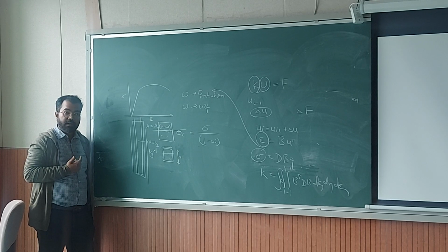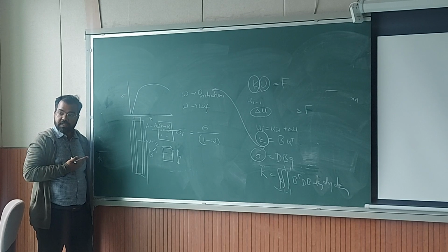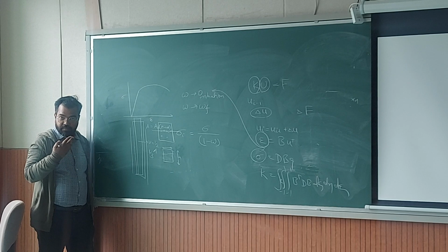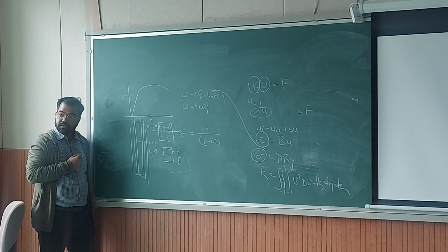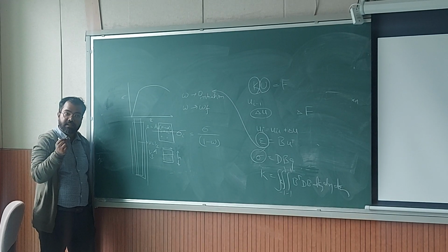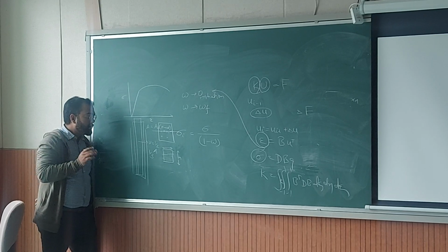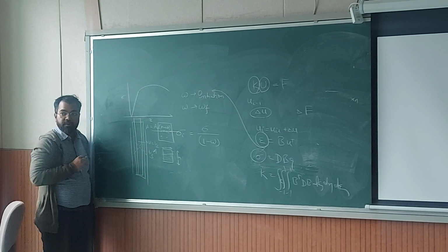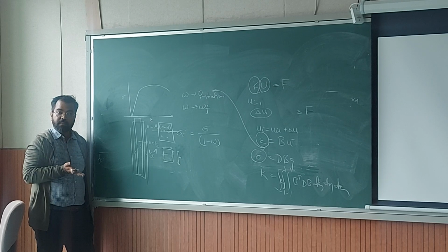And how do you simulate necking? Because damage also can develop anywhere, but damage will be developing based on the criteria of your definition of damage initiation. So damage initiation will be happening where your equivalent plastic strain is maximum. Suppose that's the criteria. So your maximum shear stress is going to be like this for uniaxial condition, 45 degree. Sigma 1 is maximum, sigma 3 is minimum.